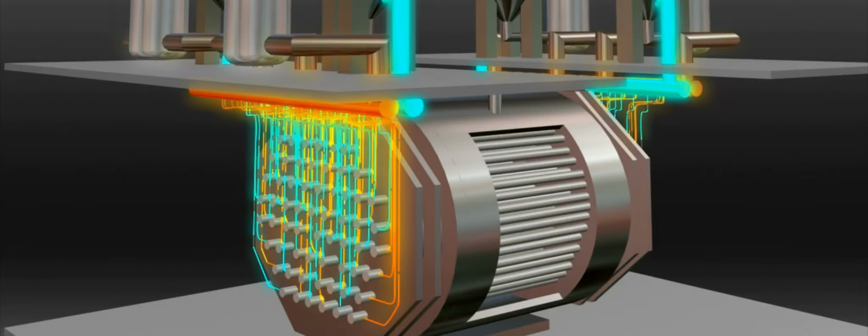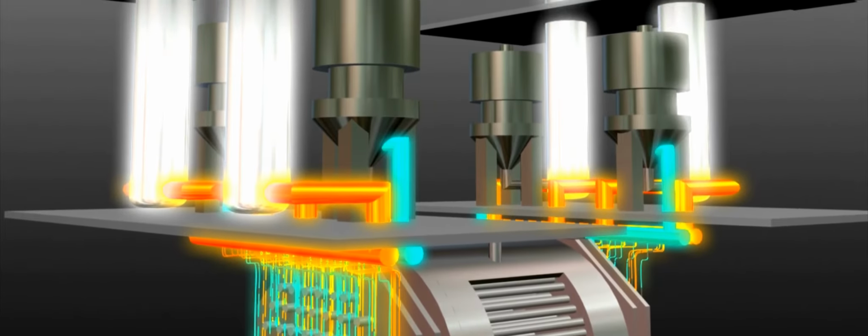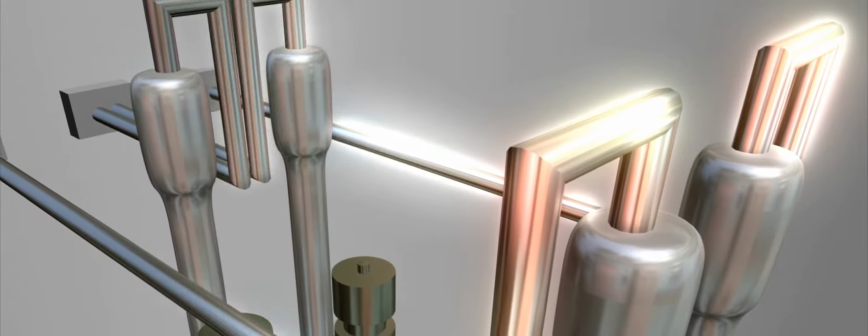The flowing heavy water inside the coolant tube transfers this heat to the 4 vertical cylindrical steam generators that are placed at a higher elevation. Upon receiving the heat, the light water flowing in steam generators in secondary circuit converts into steam. The steam raised in the steam generators is taken to the turbine in the adjacent building through the steam pipes.